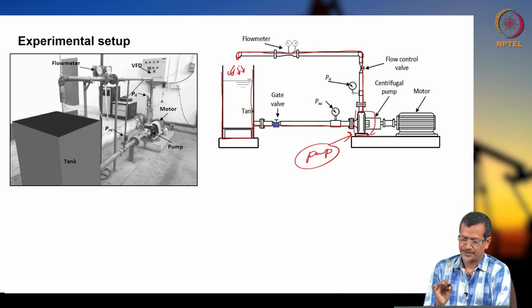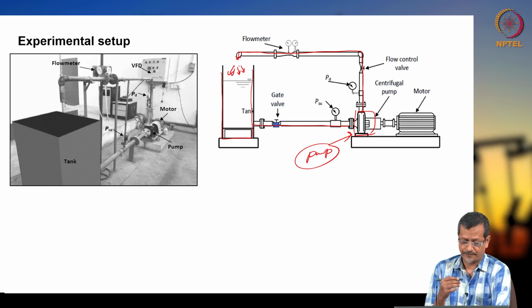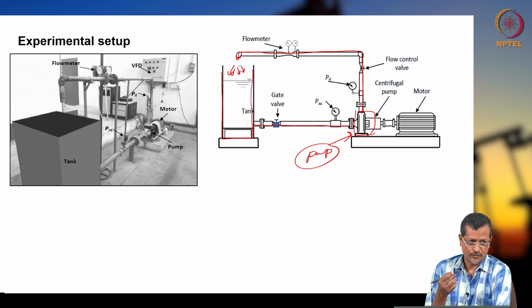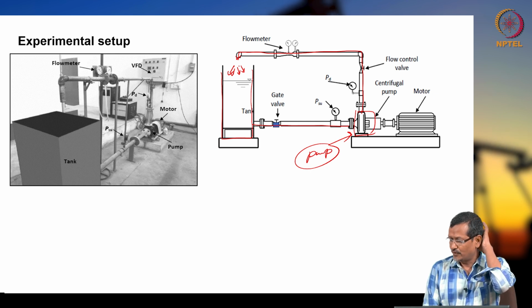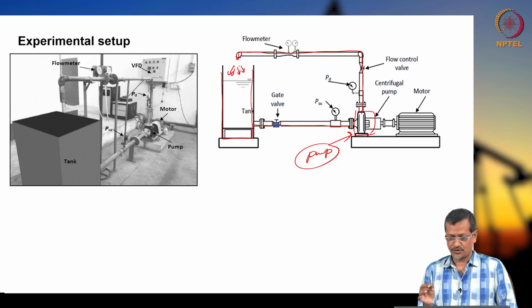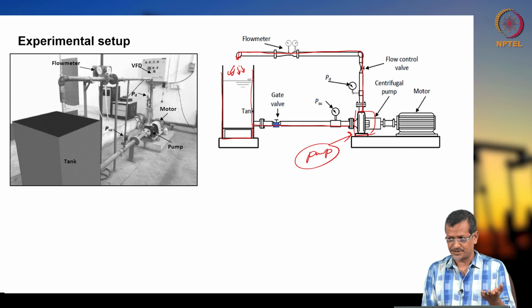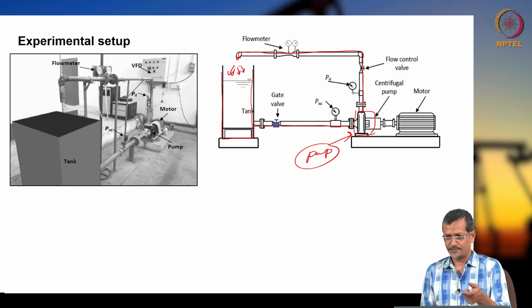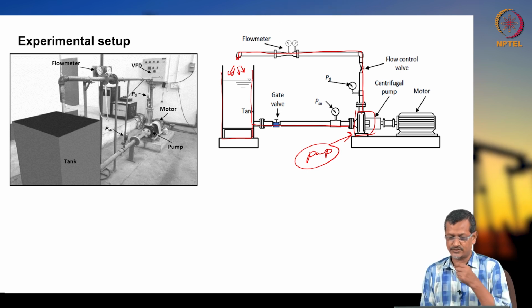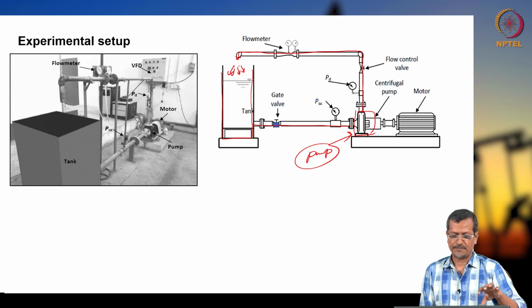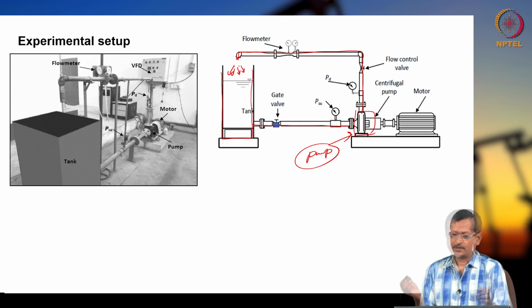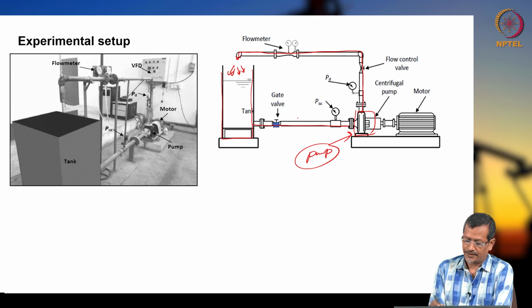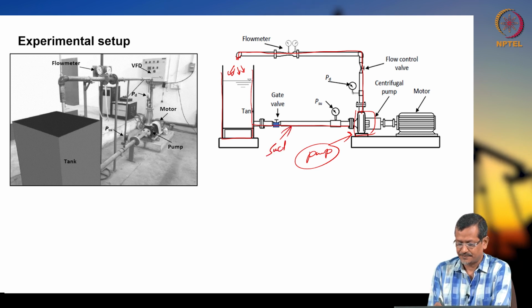Why am I showing this one? Because I used different fluids like drilling fluid. We use crude oil for pumping, and we want to check what the performance of the pump is. Instead of water, if you are pumping crude oil, with different viscosities, or different slurries, if you mix bentonite, then what will be the performance? A few PhD students have done research on this and got their degrees also. They did design optimization and played with different viscosities. Now, this is called the suction pipe.